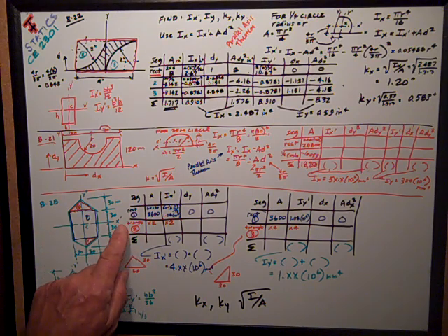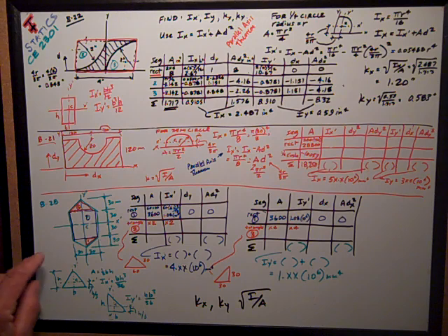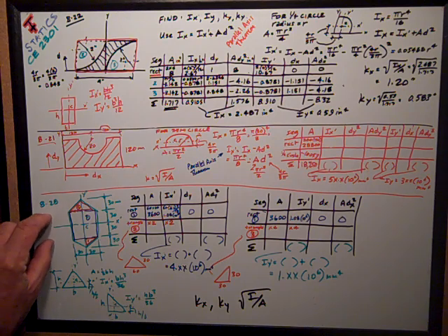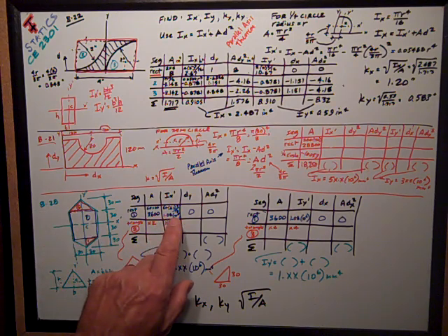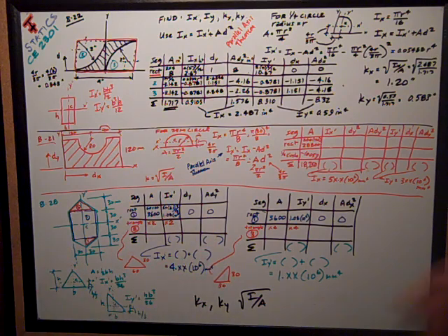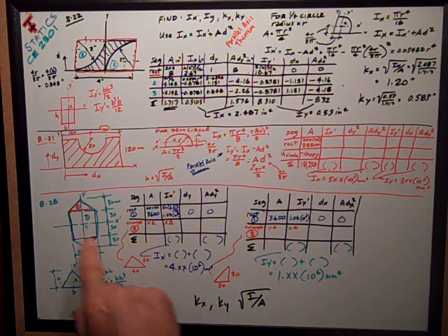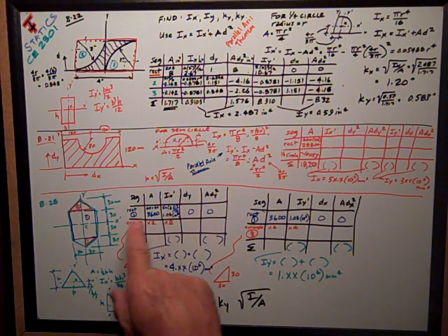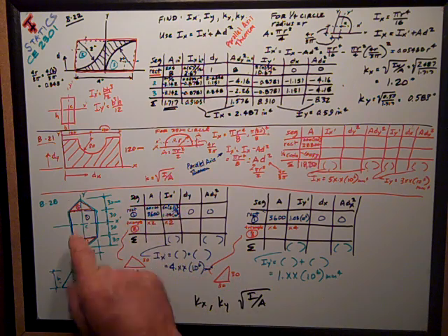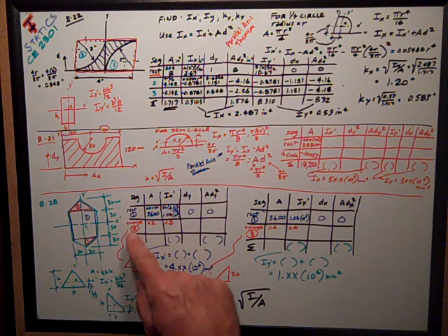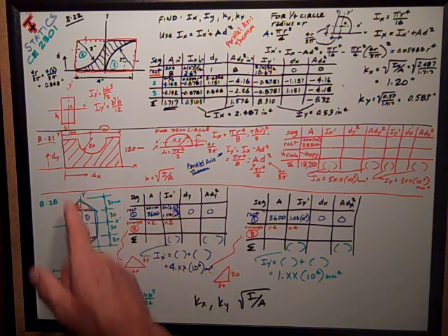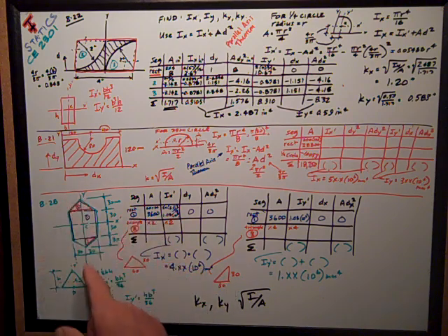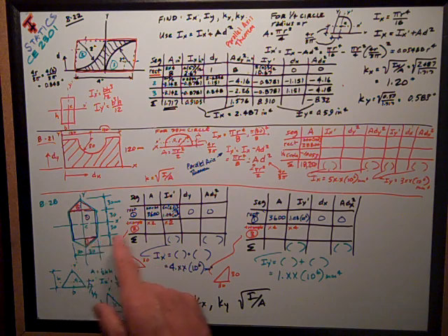Here's the X prime. What I want for this problem is to find the moment of inertia about its own centroid. So I got to break it up into 2 parts due to what I know about triangles. For Ix, moment of inertia about its own centroidal horizontal x prime axis, which by symmetry is right in the middle for both axes, x prime and y prime.